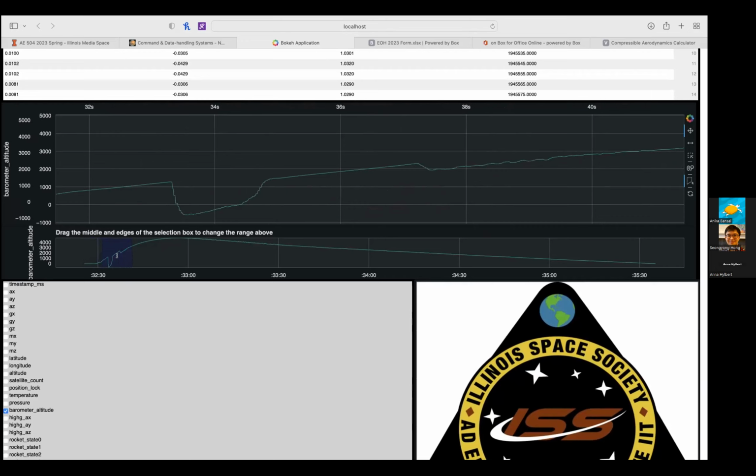That's because our rocket this time, and also in New Mexico, went faster than the speed of sound. And when that happens, the fact that we use barometric altitude means that there's such a big spike in the dynamic pressure, as Sanyan has explained, that the perceived altitude that we calculate goes down because the pressure goes so high. And then when we leave that, we have a secondary dip that is smaller, but it's still there. I don't know, Sanyan can talk a little bit more theoretically about why that happens, and I can continue. But yeah. Yeah, sure.